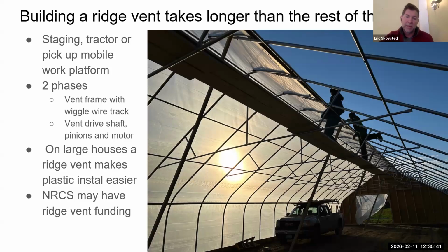Ledgewood doesn't offer ridge vents just because they are complicated, and so it's a lot of on-site fabrication of just stock components, a lot more measuring and assembling, and it's all up super high. Related to that, for any greenhouse, when we build it, we use a truck. You can see the truck down below with a ladder rack, full set of staging on top of it. That's a nice moving platform. With 3 guys, you can get a lot done that way. And then we carry about 100 2x10s on the farm at any given time. And those are great staging for things like working on a ridge vent.